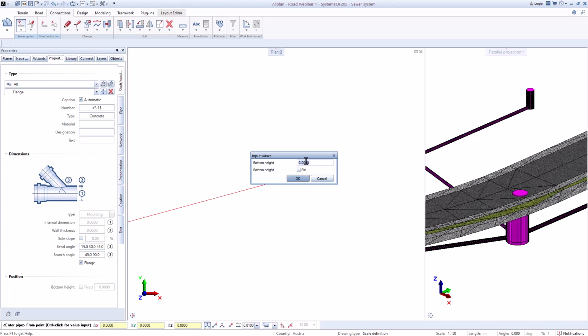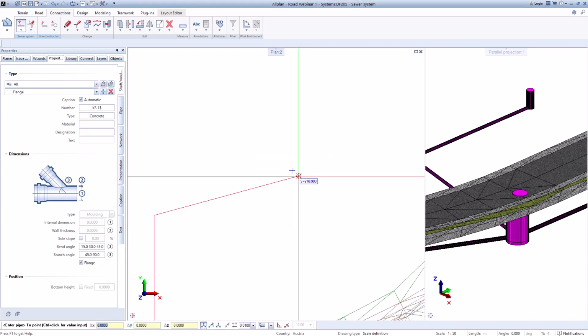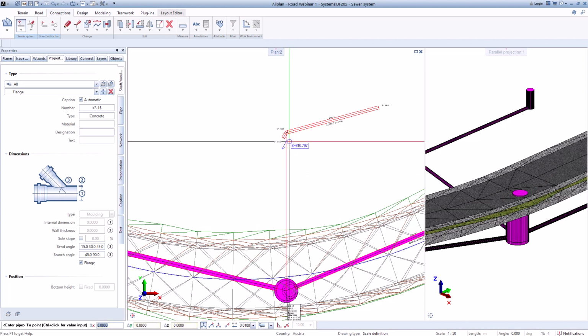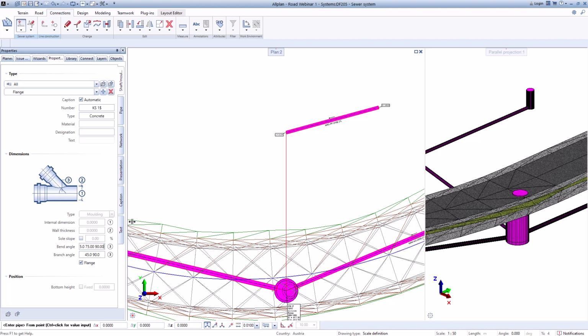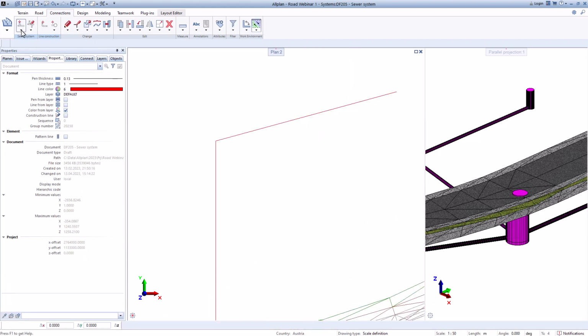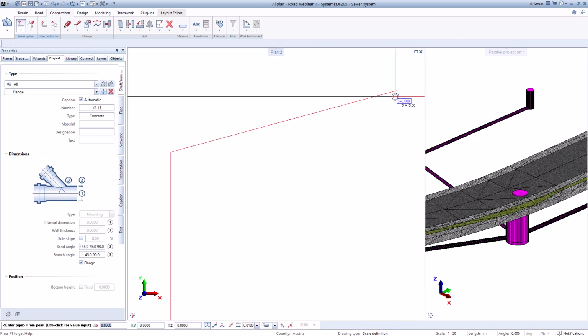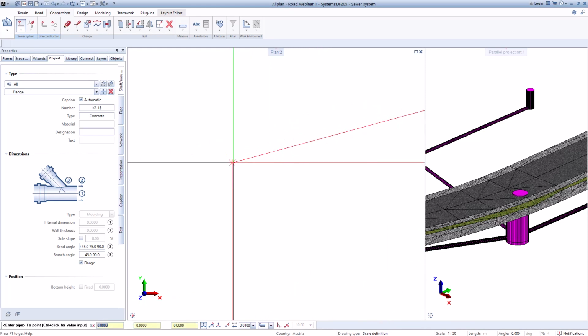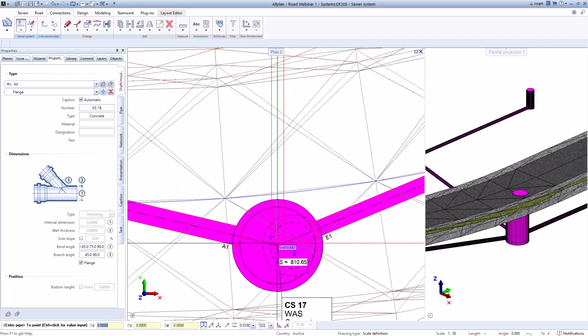The same procedure. Click, point, Control, click on the point, put the elevation, the bottom of the pipe. And I will show you here that you have only these bend angles set, but you can set another. You see now I'm typing other angles, and here I will delete what I did, and I will go again with new angles. So you always put the angles that you need. Elevation again, and now you will see that the pipe goes to the other angles that were set.